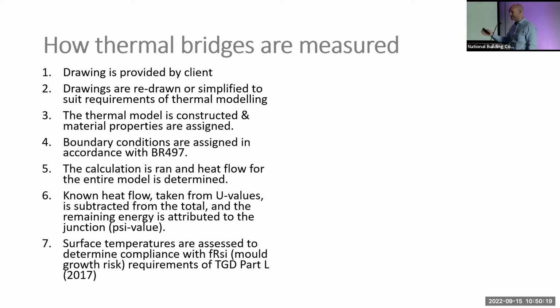And you run through a lot of different things, thermal break thickness and what the performance might be and where the angle is going to go, and concrete versus pressed metal sill and all this kind of stuff. And everyone's happy. And then you see the engineer unmute their microphone and they say, well, you can do whatever you want there and this is all fine, but that angle is going to extend 150 mil down further than that to get a good fixing in the slab and not into the screed. But everything else is fine. And you're back to the drawing board to start again.